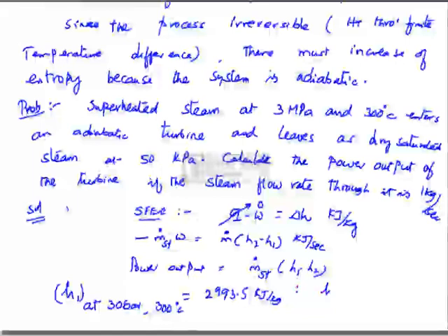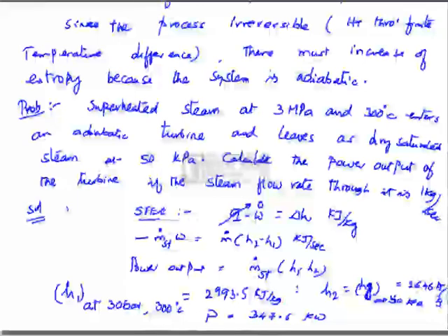And H2, that is Hg for dry saturated vapor enthalpy at 50 kilopascal, is given as 2646 kilojoule per kg. Therefore, power is 347.6 kilowatts. This is the answer.